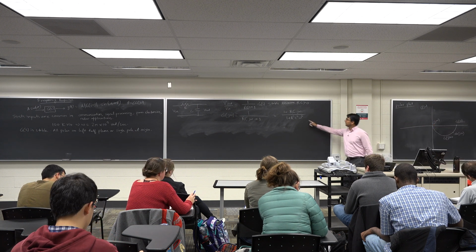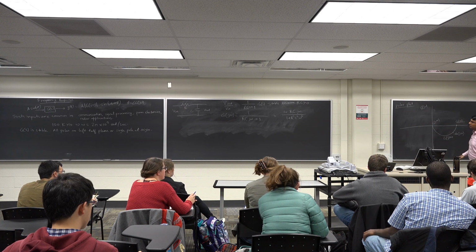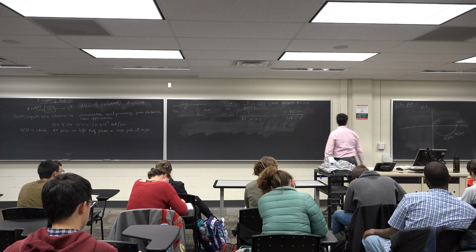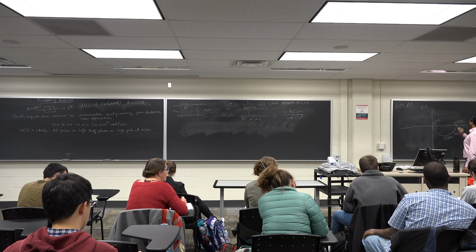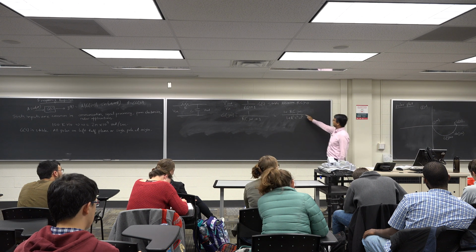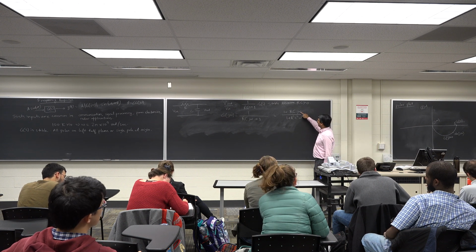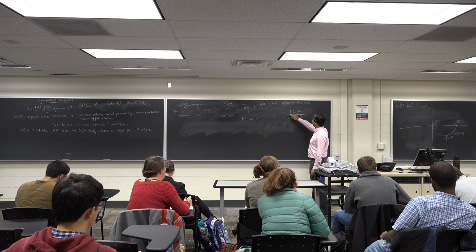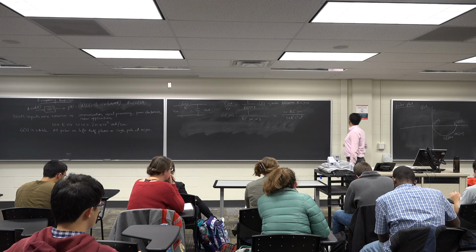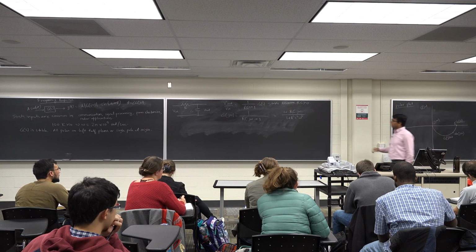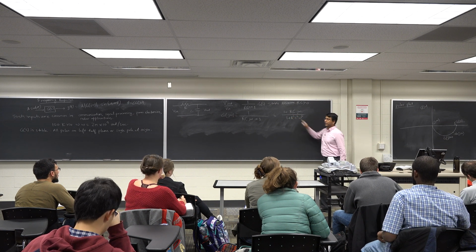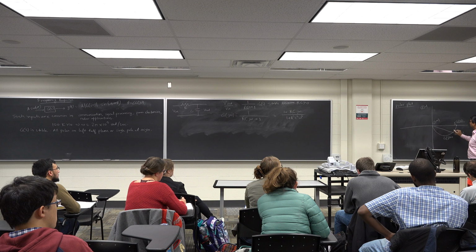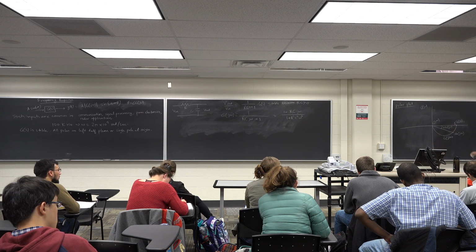Okay, let's plot this curve on the polar plot. When omega is very, very small, the numerator is 1 and the denominator is 1. So this point is exactly 1. When omega is somewhat large, the real part is 1 over 1 plus R squared C squared omega squared. The imaginary part is RC omega over the same denominator. And the phase angle of G(jω) is negative, because this term is negative. So that's your G(jω), and this is my angle of G(jω), and that angle is negative.